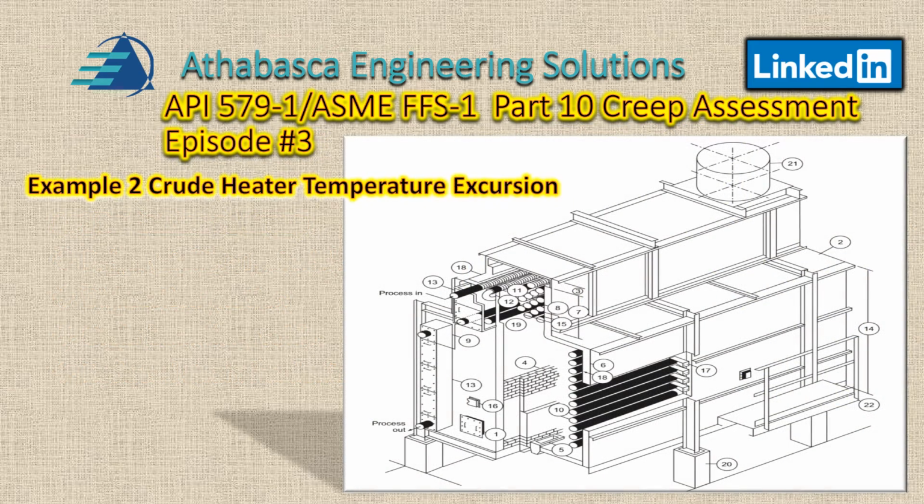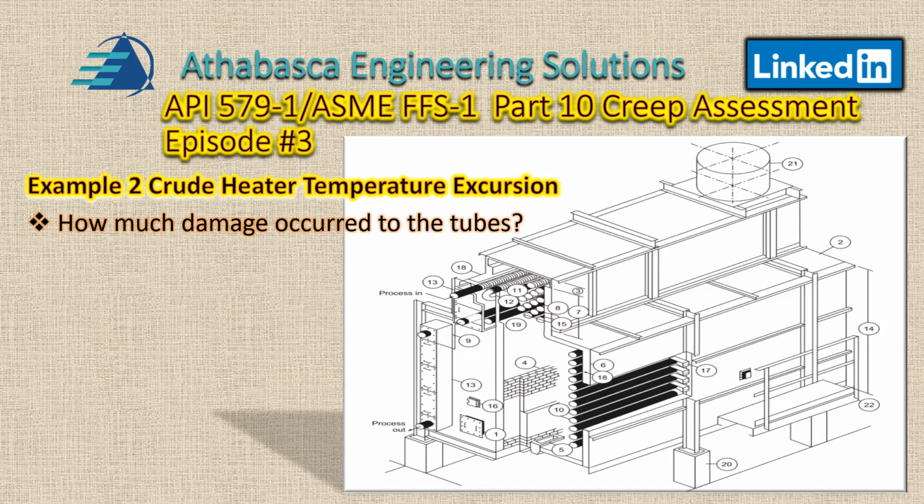Example 2: crude heater excursion temperatures. This is an example taken from API 579 Part 2, which is the Example Problem Manual, 2009. It's a pretty interesting problem. In this case, they want to determine how much damage occurred and to determine the remaining tube life.